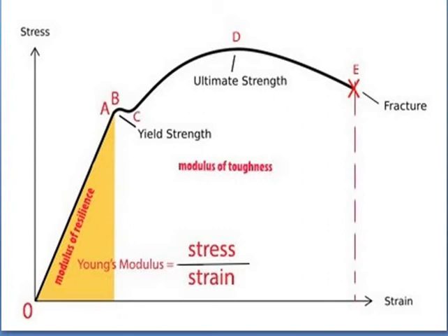After the elastic region, we have the yielding region. If the material is stressed beyond the elastic region, the plastic stage will be reached. On the removal of the load, the material will not be able to recover its original shape and size. At the point B, there is an increase in the strain without appreciable increase in the load. Thus, the curve drops down to the point C. Then again, there is an increase in the load, and strain increases practically constant up to the point C.